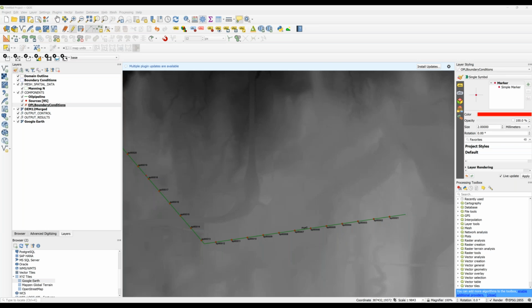Can check valves preventing backflow be included? Not now. Again, the valves are very simple. So in this version, it assumes that they close, so they do not allow any flow across them whatsoever. They are not check valves. They are just standard close valves.